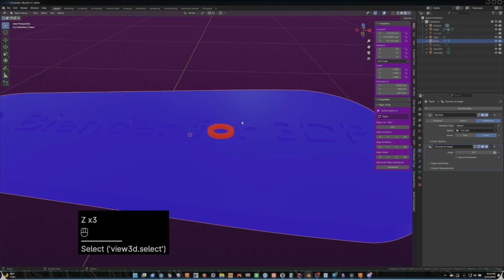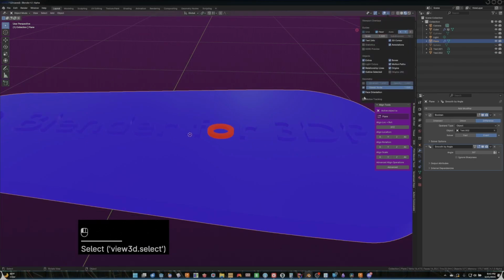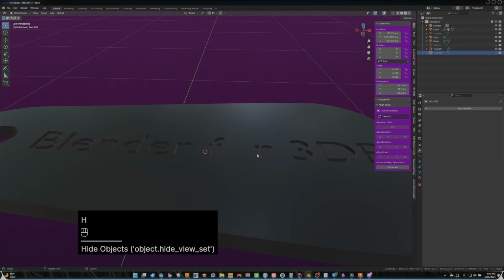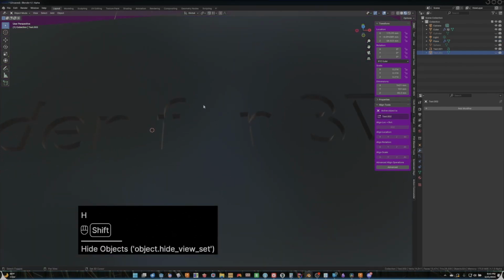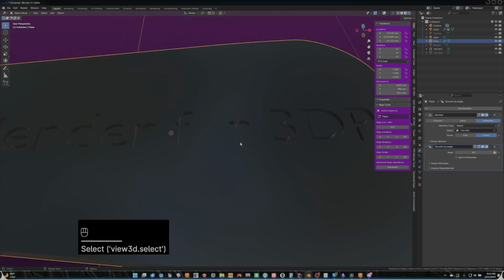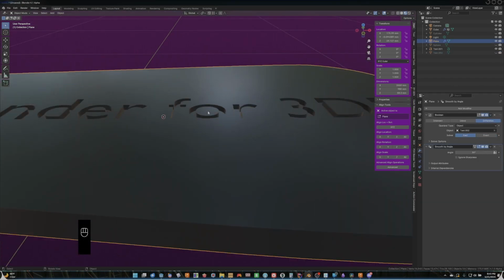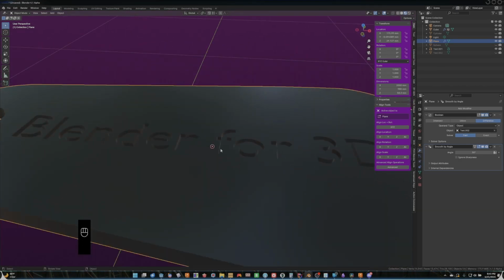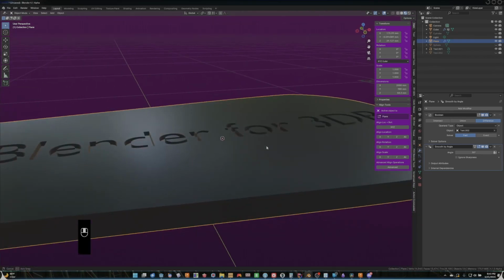But you can see that the O is inverted. We'll switch off face orientation. It's very bright. And now if we look, you see the O is missing. When I flip the normals, the Boolean operation was unable to resolve it. Even if I turn it on fast, it may show up, but it's going to be imperfect. There are going to be things in slightly more complicated geometry you're going to run into.